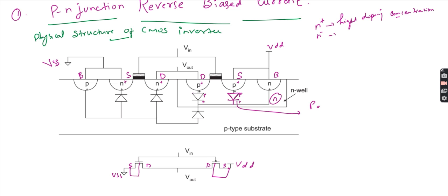This diode is a parasitic diode. It will form a parasitic diode in the bulk of the silicon substrate. You can see internally, it will form a diode here actually. So here we can see it is VDD. So this N, right, positive, VDD is positive. Then here the bulk is N substrate. It is an N actually. So positive is connected to the N substrate. So I can say it is here reverse bias, correct? It's a reverse bias.